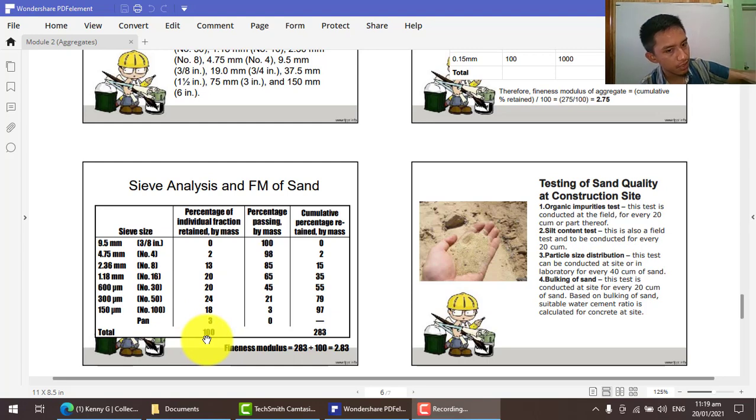Whatever will be retained should be a total of 100. By the way, the very, very small sizes will pass to the very smallest size of the sieve, and will be retained if you put a pan. Of course, that is a very tight, closed, impenetrable pan. So whatever passes through to the very smallest will remain on the pan. If you consider that, it should add to 100%. It will go to that original total of the weight if you are using weight by weight.